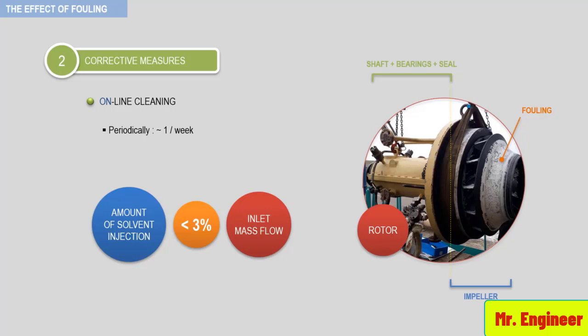Process and compressor designers should be consulted regarding the exact procedure to be used. However, I strongly advise you to use a radial vibration trip system if online cleaning methods is to be implemented. This action will prevent catastrophic compressor failure in the event of an incomplete online cleaning.